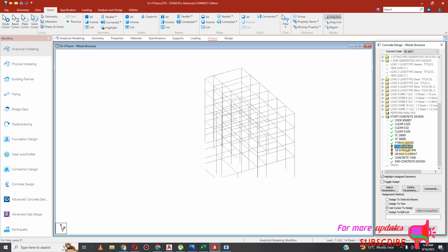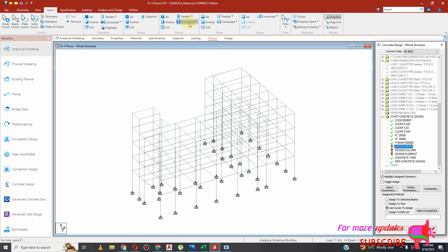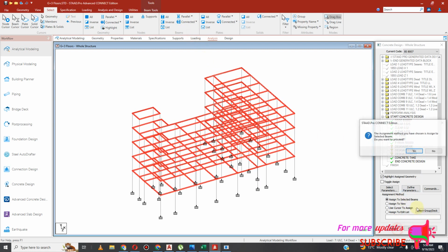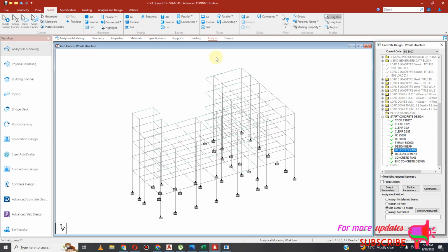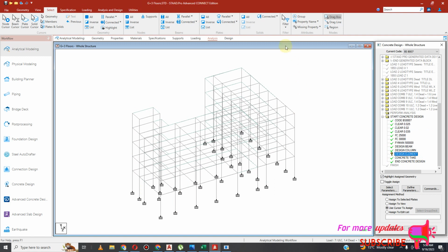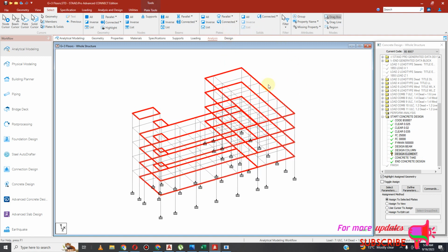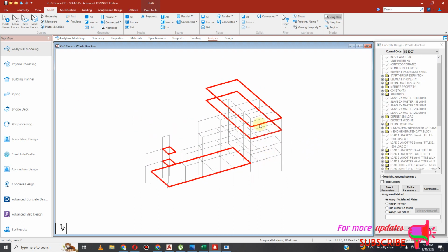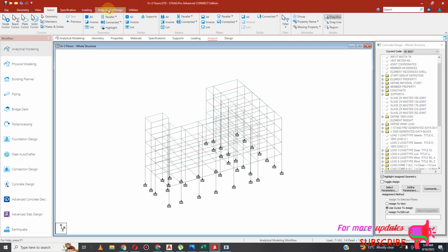Yes. Design beams assigned to parallel to X, parallel to Z, assigned to the selected, assigned, yes. This one assigned to parallel to Y, assigned to the selected, and then assign, and then yes. This one I assigned to plates ZX, assign, then yes. Then I will save. Then I perform my analysis.